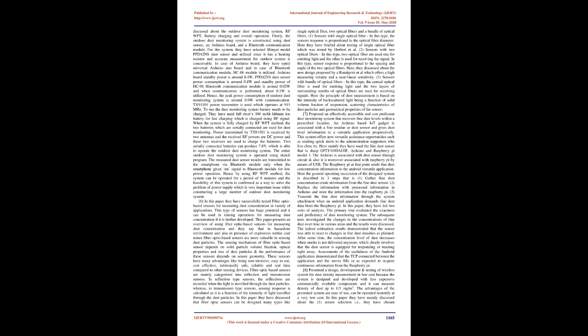In case of Arduino board, they have opted for Universal Arduino Uno board, and in case of Bluetooth communication module, HC06 module is utilized. Arduino board standby power is around 0.4 W, PPD42NS dust sensor power consumption is around 0.4 W and standby power of HC06 Bluetooth communication module is around 0.02 W, and when communication is performed, about 0.1 W is utilized. Hence, the peak power consumption of outdoor dust monitoring system is around 0.9 W with communication.